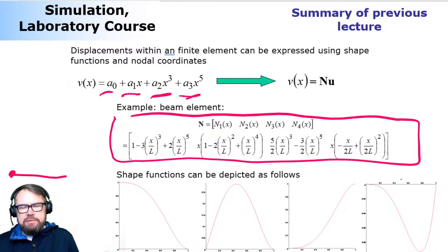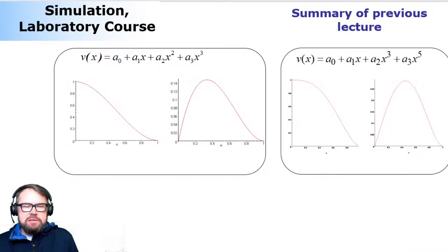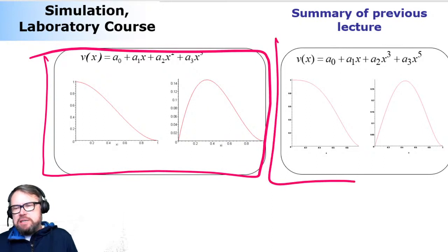So if again I have this two node beam element, the first degree of freedom is moving this node in a transverse direction. You see that that's exactly what happens here. Tangent here is 0, displacement here is 0, tangent here is 0. This looks a little different when comparing the previous set, and this is a rotation of the same node, and these are the mirror images. So they look different. This is summarizing that. This is what I use as a conventional way, and this is my additional way.